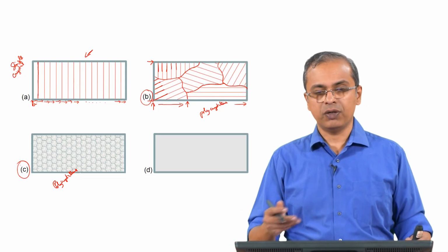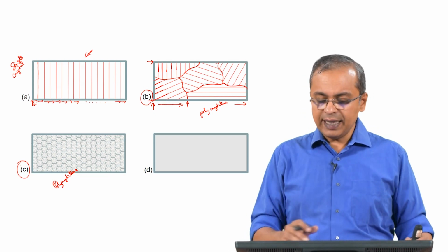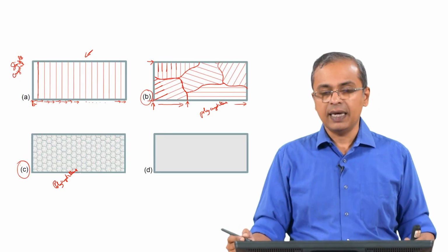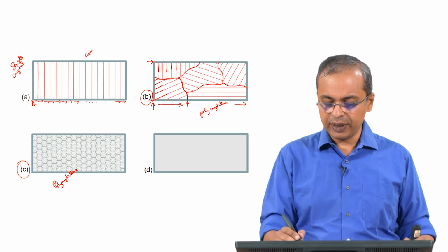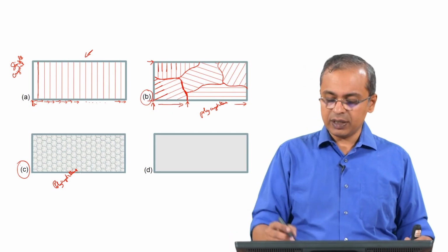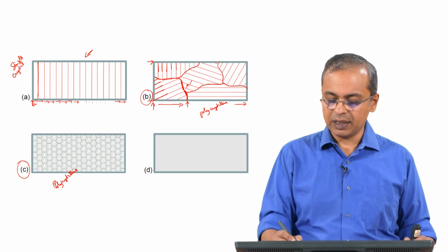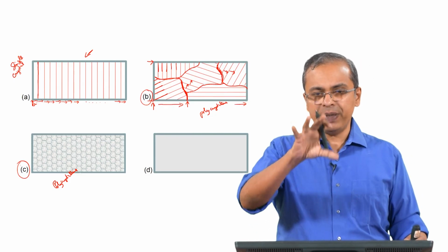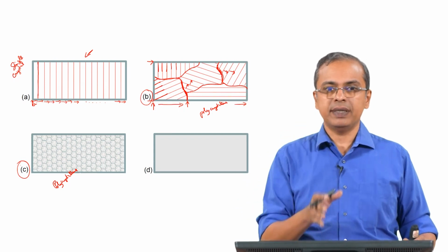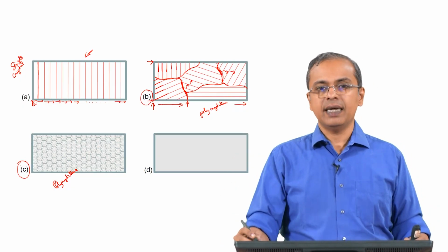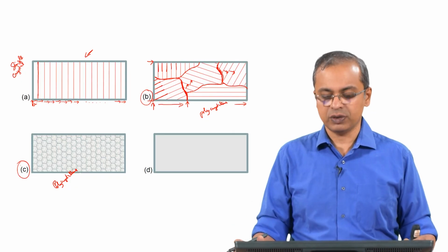You may have had 3 divisions in the middle, you might have had 100 divisions in the middle and so on. So, this idea that you have crystalline order only up to a certain location, and then after that there is a breakdown of order, at least at this boundary area, and then again order starts in this location. So, you see some crystalline order in that location, again order breaks down in this region here, and then once again you have crystalline order. This idea that you have pieces of crystalline order with boundaries in between them is referred to as a polycrystalline situation. Okay. So, this sample is polycrystalline in nature, it has many crystals, that is why polycrystals, which are distributed across the sample.